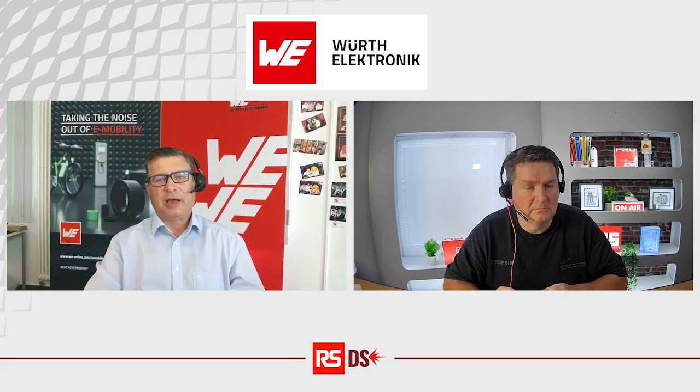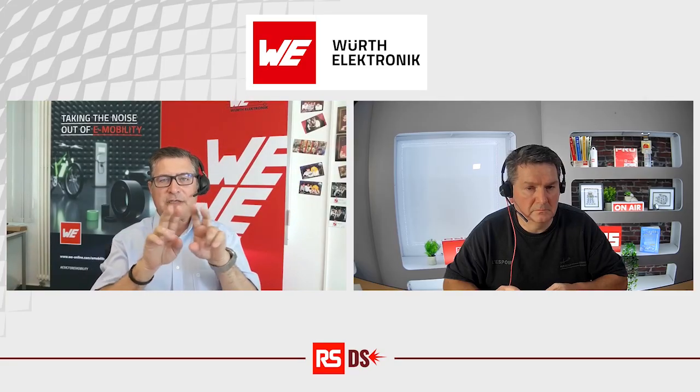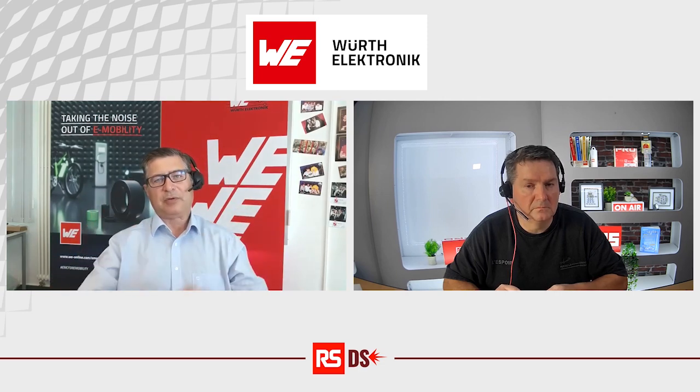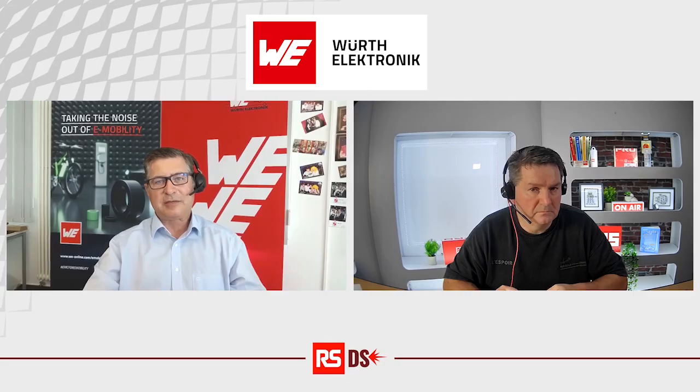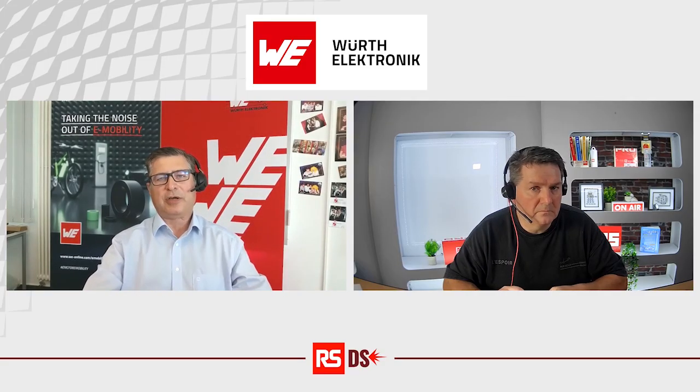Instead of using one, I prefer to use at least 2 of them, or maybe split it into 3 times 32 microfarad capacitors. It's much better behavior because each capacitor has its ESL, ESR, and the resistors are in parallel. It's getting smaller and smaller, and then automatically my ripple goes down, and I have less problem with ripple current or damage to the capacitor because of the ESR issue. I like to always do some splitting of the value. Whether it is an input capacitor or an output capacitor, I try to do the same.